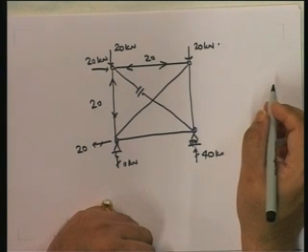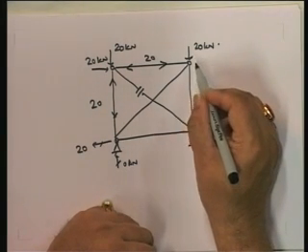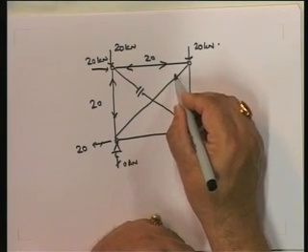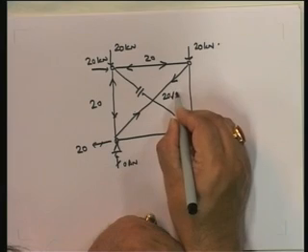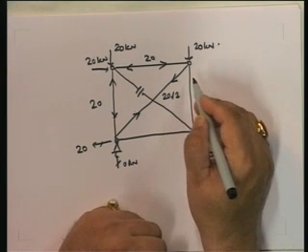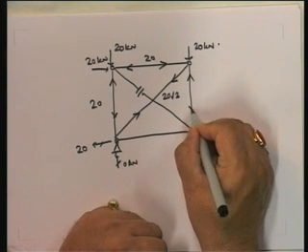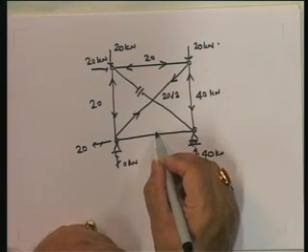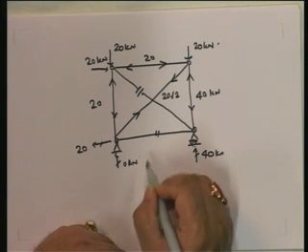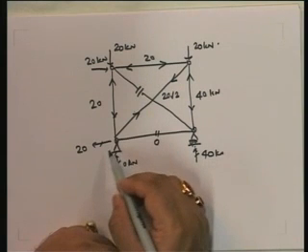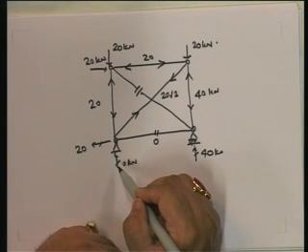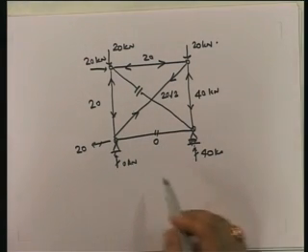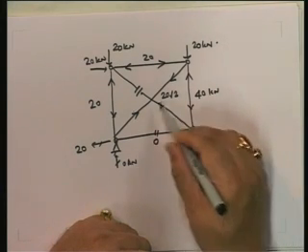Okay. And then what else do we have? Let's look at this particular joint. In this particular joint, the horizontal of this is going to tie up with this. So this is going to be equal to 20 root 2, and therefore this is going to be equal to 40. And if you look at this, this is going to be equal to 0. You will see that at this particular joint, 20, the vertical matches with this and the horizontal matches with this. So this is 0, this is 0. Here there is only vertical, so this horizontal is 0 and this is anyway 0.